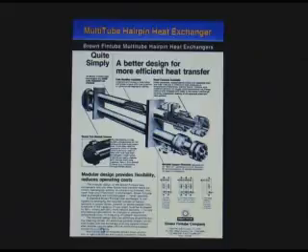One of the main issues of these units are these tube side closure here and the shell side right here. Currently, we've experienced difficulties satisfying external piping loads because of the mechanical design of these units.